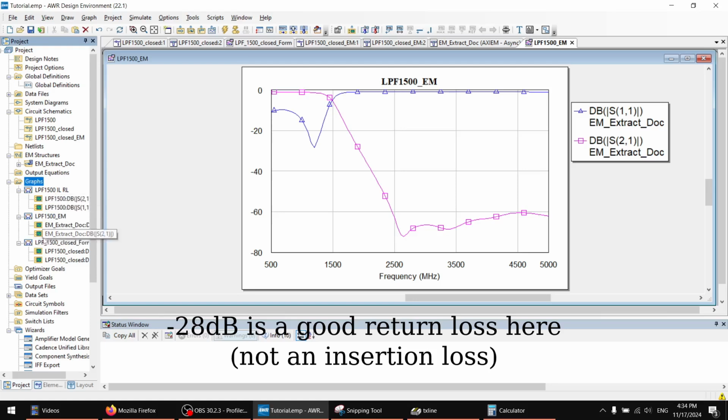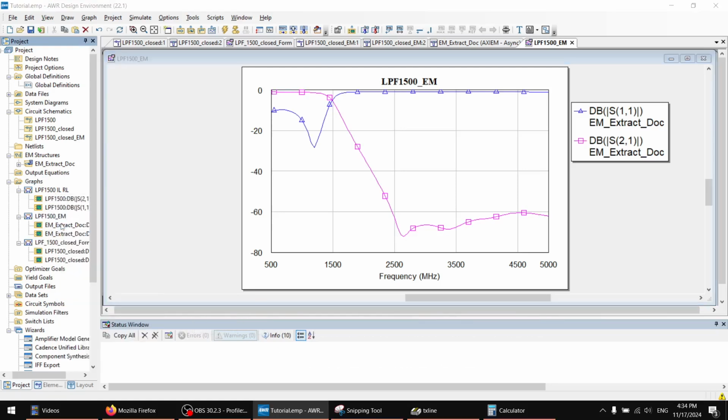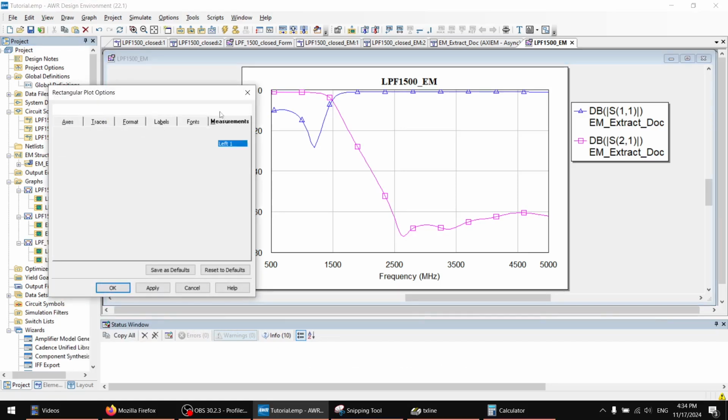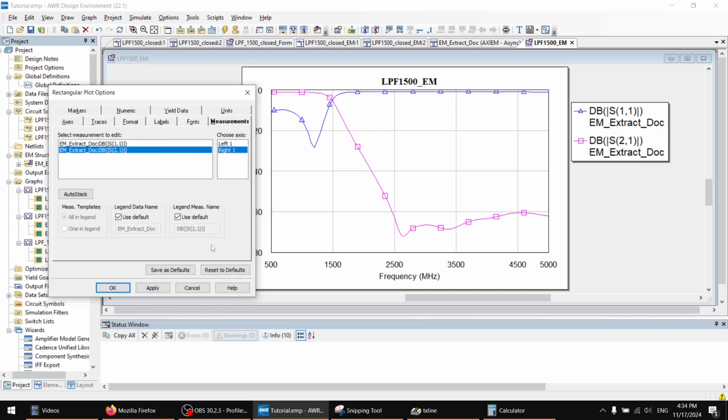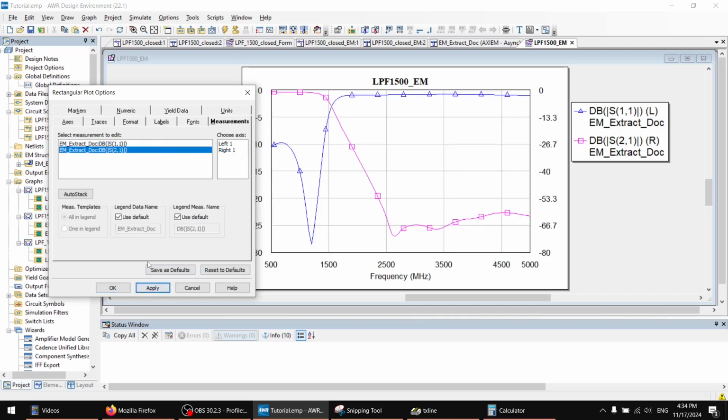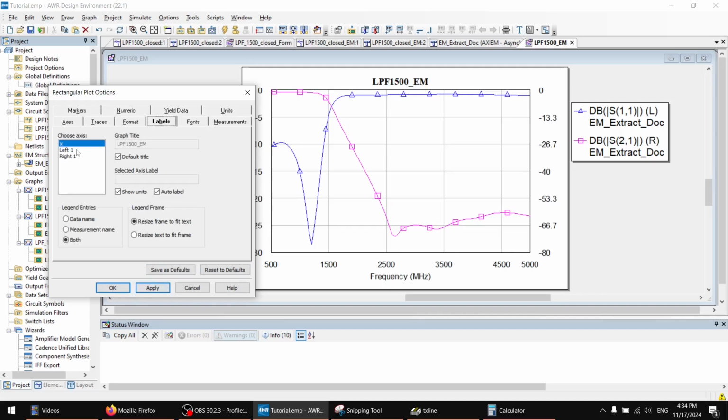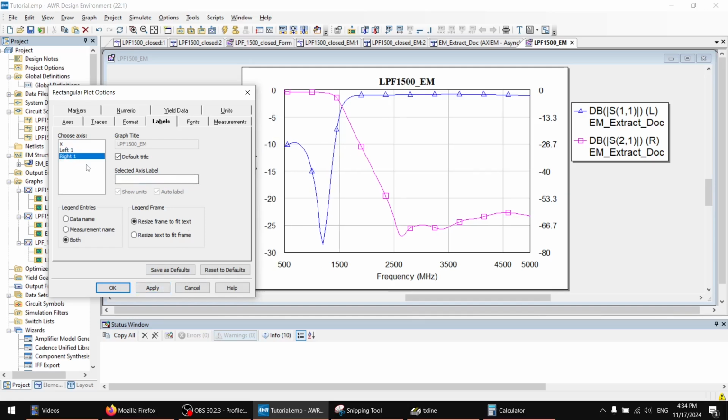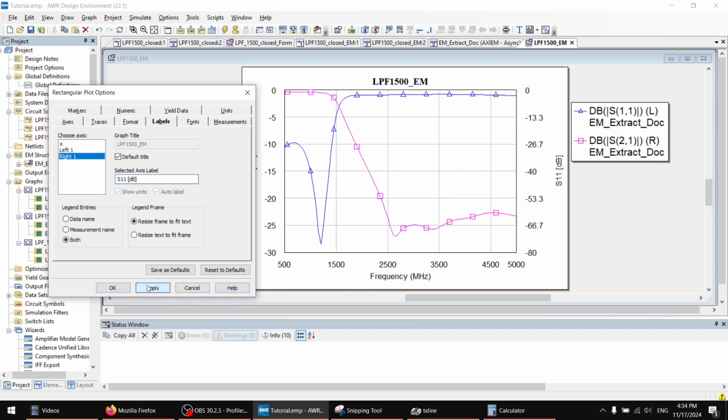Let's maybe do as an exercise again, setting up this measurement to the right side quickly. So this is on the right side, and now put the labels on the left. This is S21, of course, in dB. All right, and I guess left. Now it's right, and this is S11 in dB as well. If only I could put the brackets in the correct order. Right.